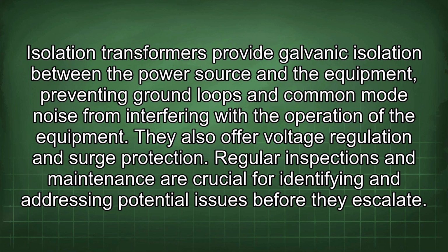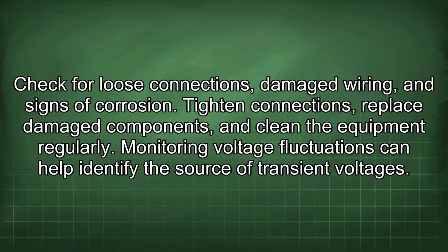Regular inspections and maintenance are crucial for identifying and addressing potential issues before they escalate. Check for loose connections, damaged wiring, and signs of corrosion. Tighten connections, replace damaged components, and clean the equipment regularly.